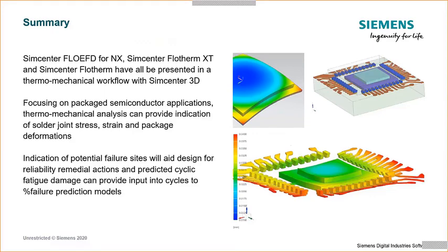Probably more importantly, indication of potential failure sites in terms of maximum stress or maximum strain and displacement. And this information can help to aid design for reliability remedial actions. And then in terms of cyclic transient simulation, the predicted cyclic fatigue damage value can provide input into cycles to percentage failure prediction models.